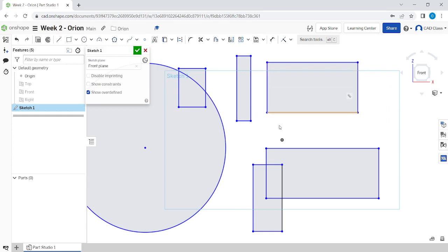Now, if I wanted to select everything the box touches, I have to go the other way. I have to go right to left. So I can start over here and select right to left, and you'll notice it selects the vertical lines. That is very important. It won't take very long before this becomes muscle memory of which way to go. Having both of those modes available to you is super useful when you start getting into complicated sketches and things.